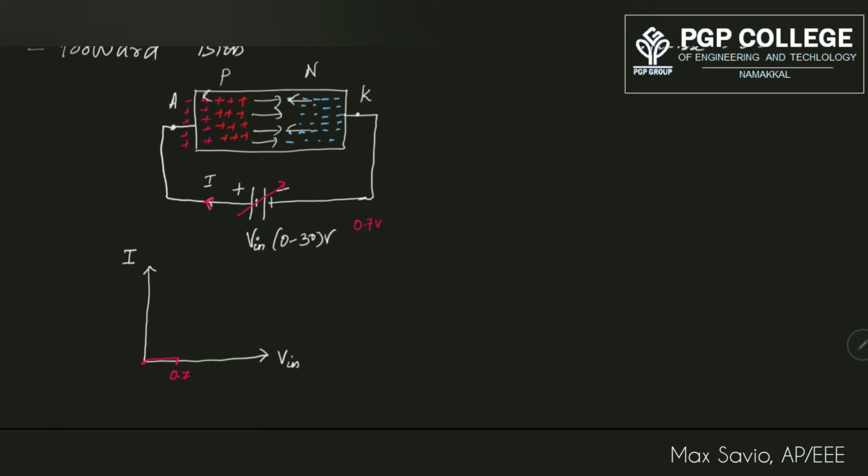It happens at 0.7 V. Until 0.7, the diffusion layer keeps diminishing, and at 0.7 the barrier or diffusion layer completely breaks and the current starts to increase. The point at which the current starts to conduct is called the threshold voltage.